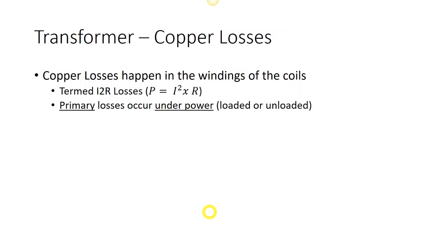Some of these packs for computers are quite large, and if you just plug it in but don't have it plugged into your computer, after a while you go over and touch it, it's warm. Those are the I2R losses on the primary side of the transformer. So you're actually spinning a watt meter and running up an electric bill, but you're not actually using any of that power.